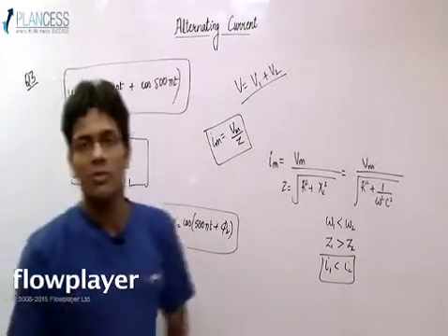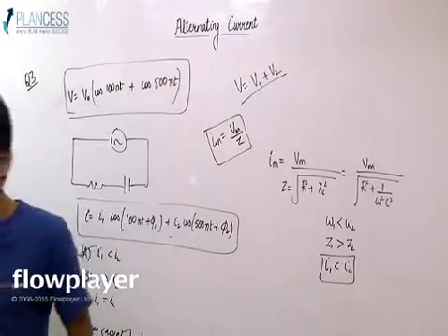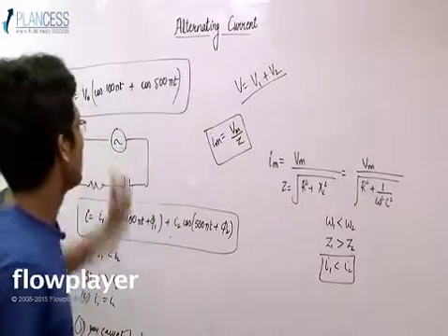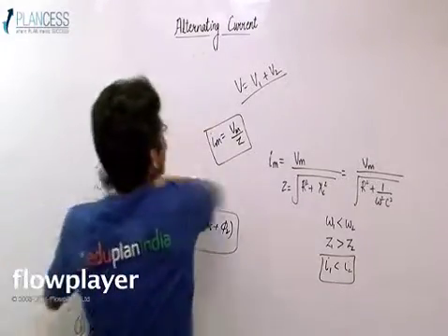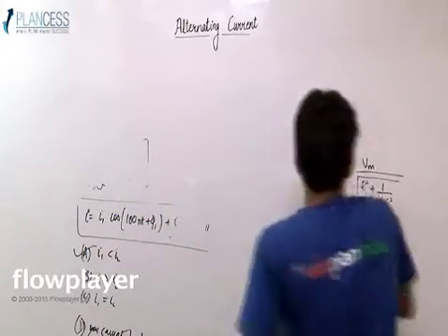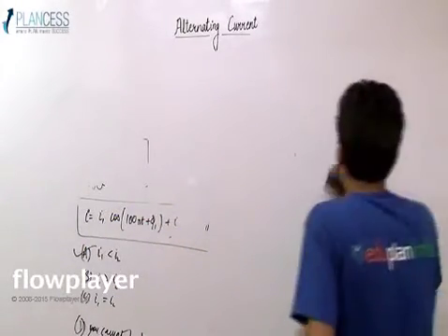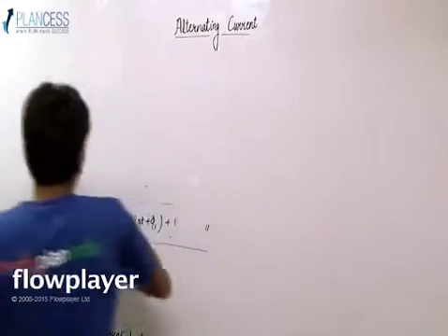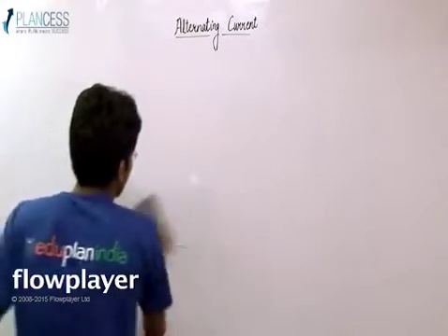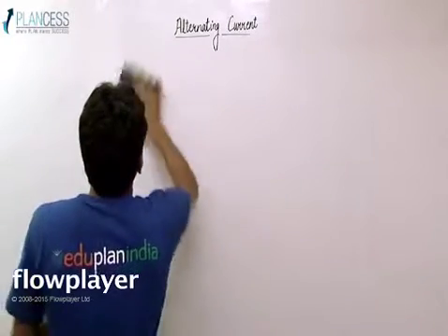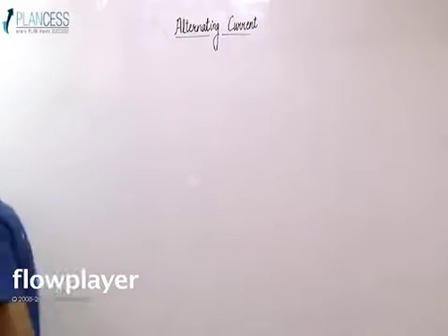So you can see this question was pretty simple if we remember the formulas and understand that if you have an AC source as a harmonic sum of sinusoidal voltages, then you will get two different values of current if the circuit has an RC or RL circuit, where omega is involved in the calculation of impedance. So this was our question number 3.